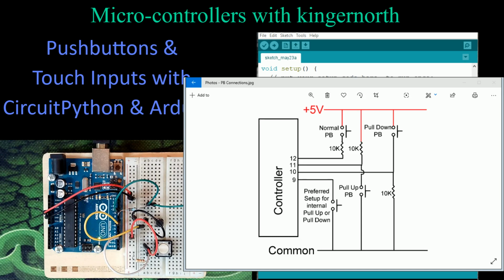And what happens is we really don't know what the voltage is on that pin 12. We don't know how much stray voltage we're seeing there, or induced voltage from other components in the area. So that's a real problem with electronics, the way they're set up. So that's not the preferred method. We would prefer not to do that in these microcontrollers.